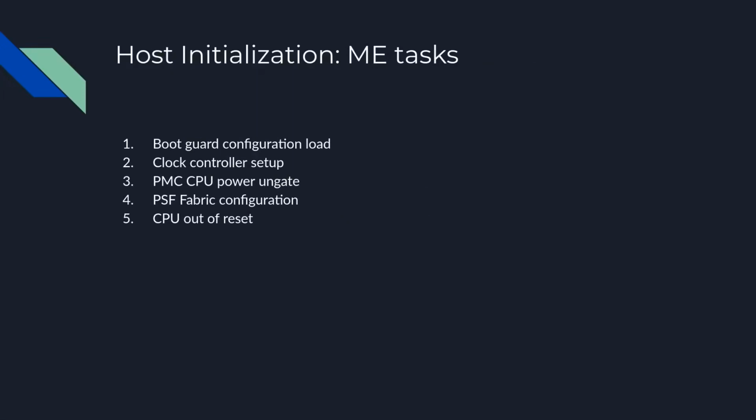It needs to load the keys for the bootguard process. It needs to set up clock controllers, and then tell the PMC to turn on the power to the CPU. It needs to configure the PCI Express fabric and reset, and get the CPU to come out of reset.